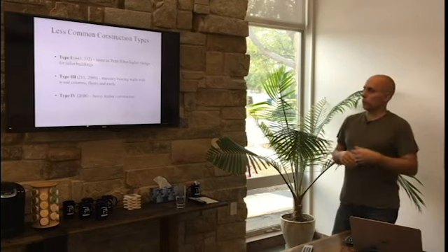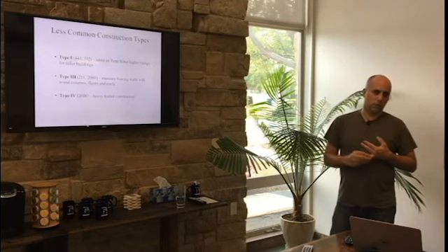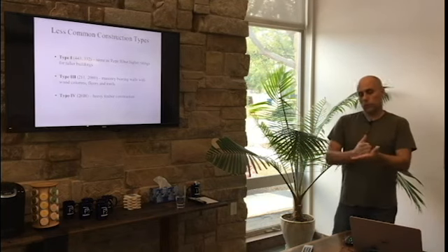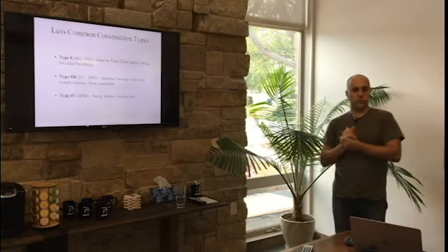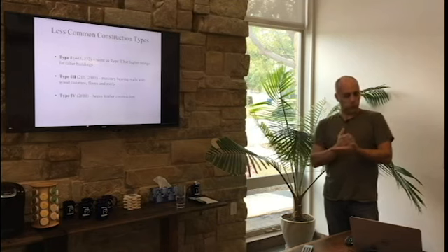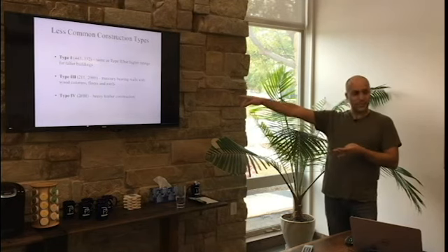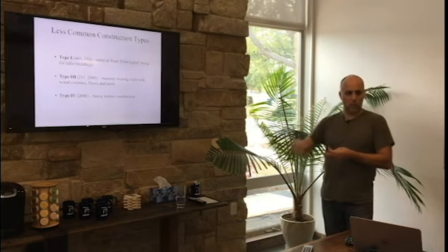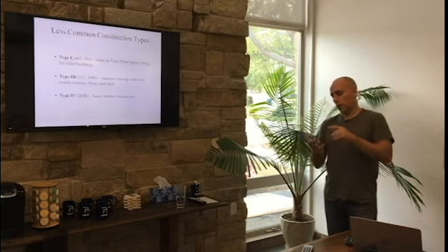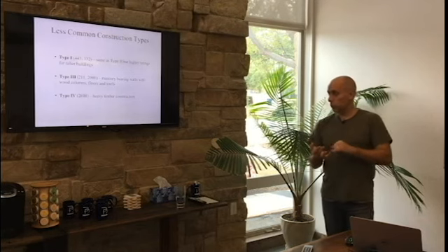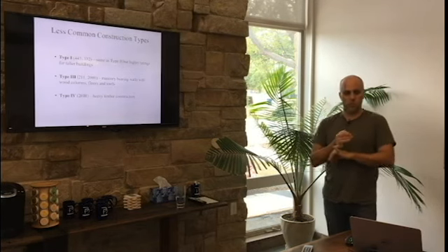Under the new version, the 2012 edition of NFPA 101, it references a newer version, the 06 version of NFPA 220, which is the construction types. It permits you to use heavy timber members as long as they meet the sizing requirements of heavy timber in type 5 construction without providing additional protection, which means connected to the building, we can do all the heavy timber porte-cocheres that we've always wanted to do.